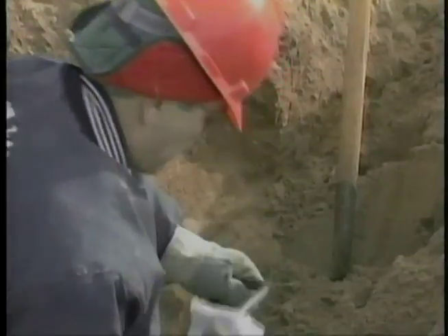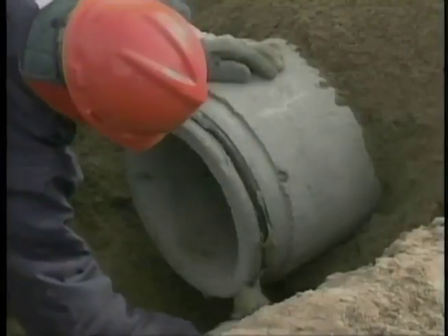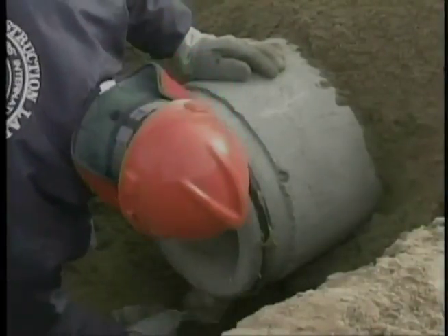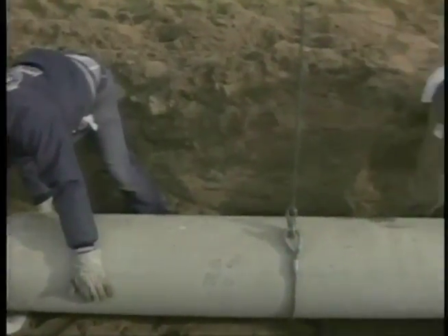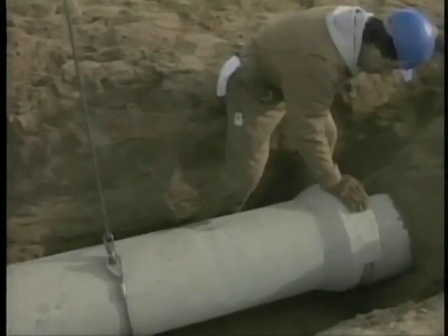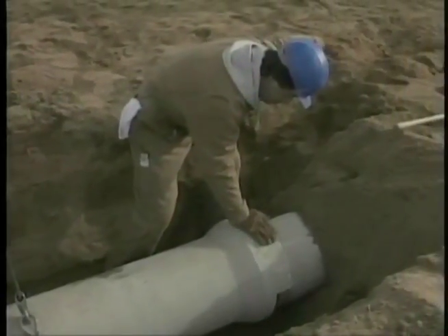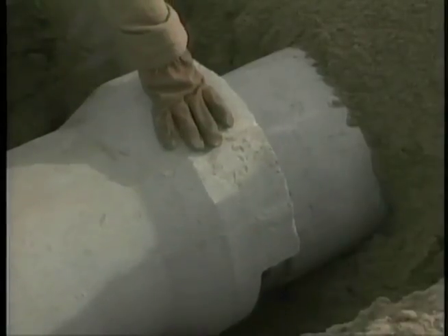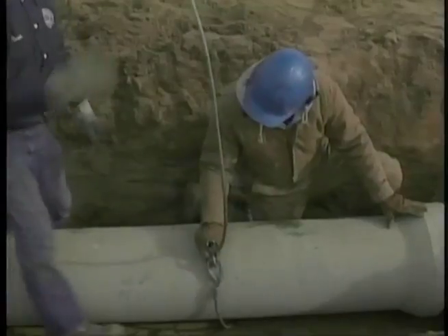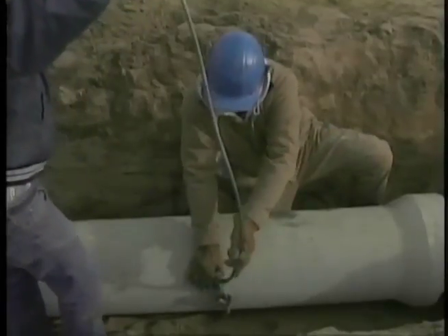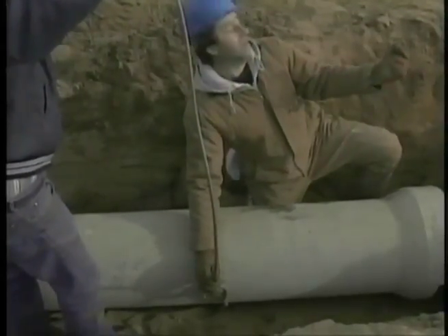Clean gaskets. Lubricate spigot and bell ends of the pipes, as with any normal joint installation. Lower the replacement pipe into the excavation with the remaining bell section on top. Slide the choker to the side of the pipe and lift to slowly rotate the bell to the bottom. While rotating, it may be necessary to adjust the choker several times to complete the rotation.